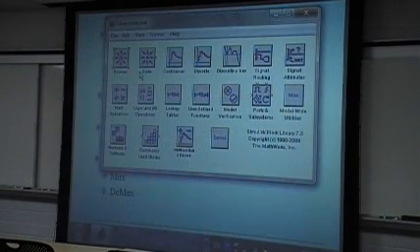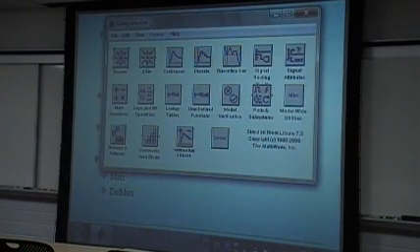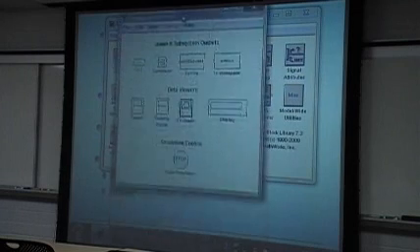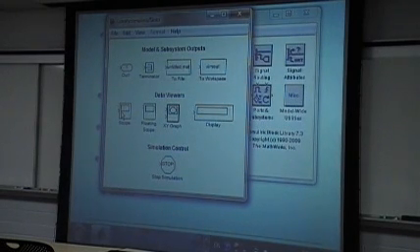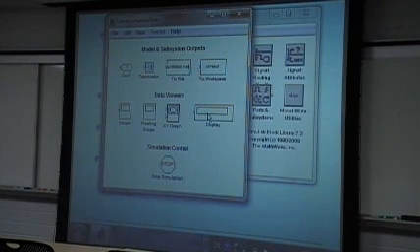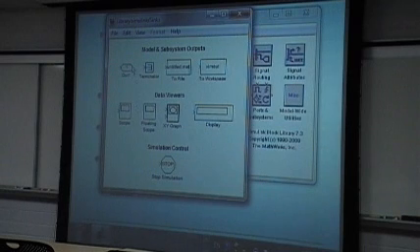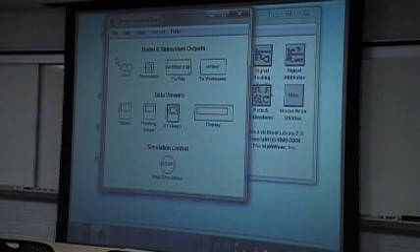And if you have created a simulation block diagram and you want to display a signal, then you can use a block in this group. In this group, we can see that you can connect a scope to the signal. We can also have a text display, a value display of the signal. We can also write the signal back to the Matlab environment. And we have a very important one corresponding to the Inport: the Outport, which allows you to indicate the output of the system.